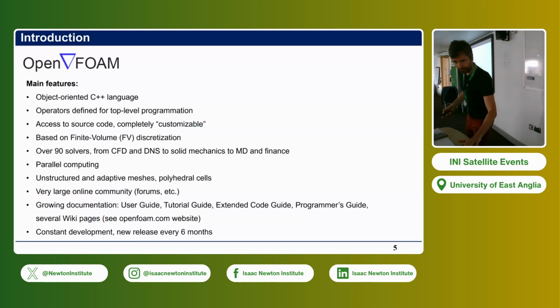I keep trying to switch slides with this one. Main features of OpenFOAM: it is written in C++. Operators are defined for top-level programming. So we will see later when we sneak into the solvers that you can solve new equations just by calling the different component terms of an equation. And the different terms will be discretized with the already available libraries to discretize a convective term in different ways. So you don't need every time to reinvent the wheel if you want to implement a new equation.